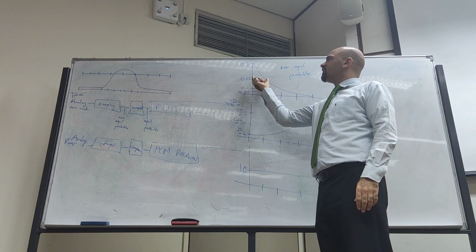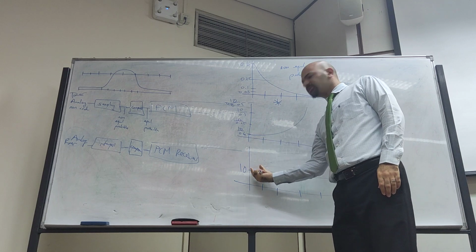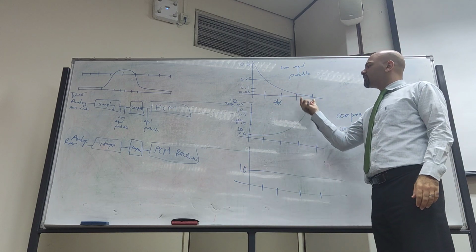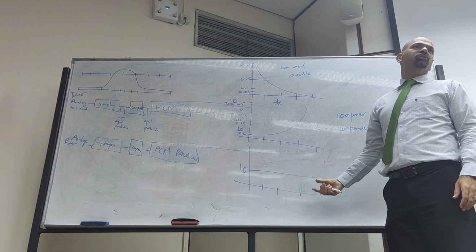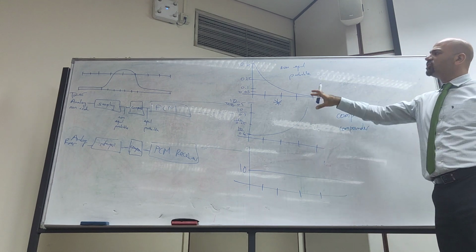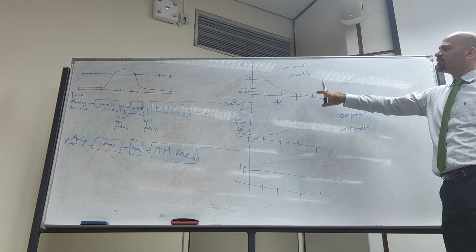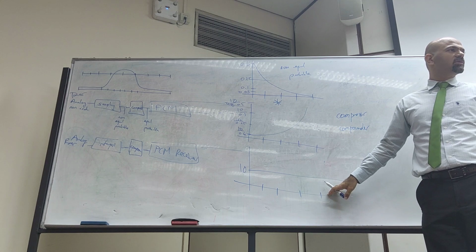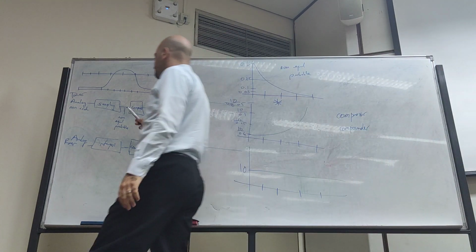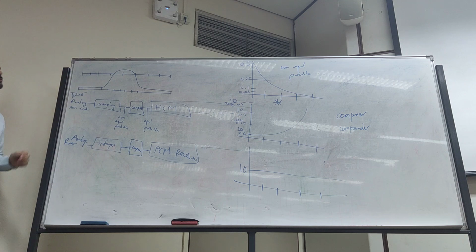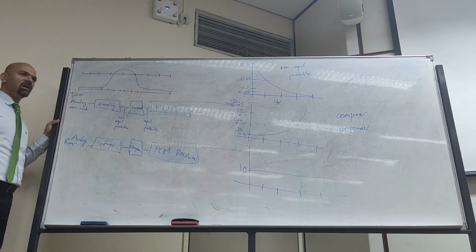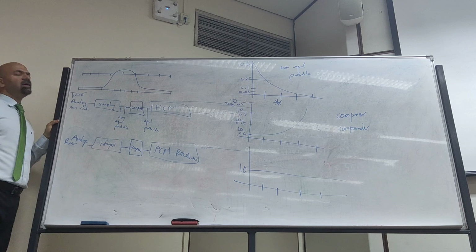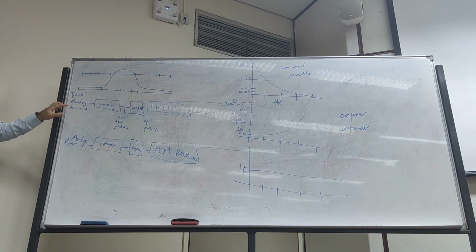So here, this area has a large probability. With this compressor, you make it smaller. This area has a low probability. With this compressor, you make it larger. In other words, this unit has reshaped the samples from non-equal probable into equal probable. Clear? This is the idea. And if you can reverse it at the receiver side, things will go perfectly. Is it clear how this will work? Our PCM is still the normal PCM, it has not changed, but with this pre-unit we fix the issue of non-equal probable.